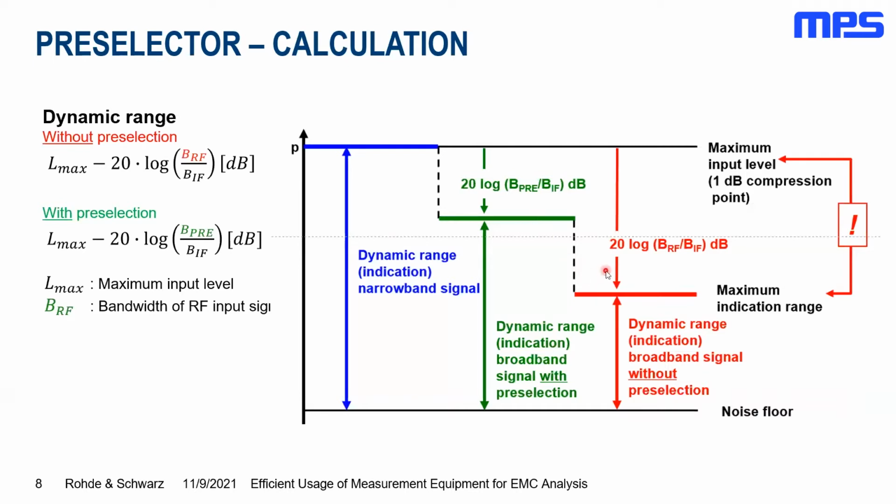It's only worth talking about a preselector when you're having these more or less wideband disturbers, meaning having some higher frequency components, meaning higher in amplitude, meaning higher in power, that is provided to the mixing process, and therefore we'll have to suppress these higher harmonics or higher side emissions to accurately measure the amplitude of these other emissions there.